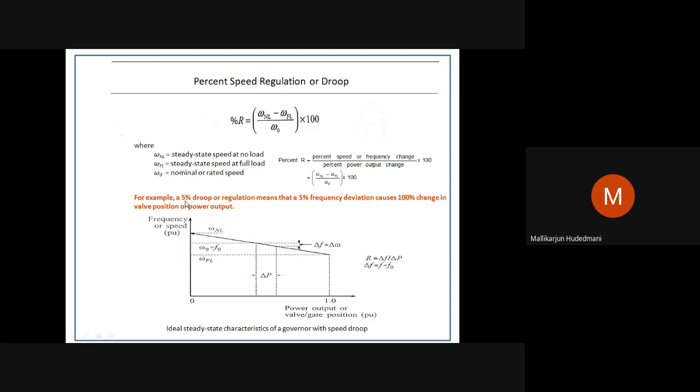So this is the meaning of droop. It may be 3%, 4%, or 6%, depending upon the machine. In that respect, the response of these generators to a subsequent load increase will come into operation. Similarly, when there is a drop in load, suddenly we have to change the set point because otherwise the RPM of the generators or turbine will ride fast. So to reduce it, what is the response of the governor as and when there is a drop in RPM, and how is that going to supplement?